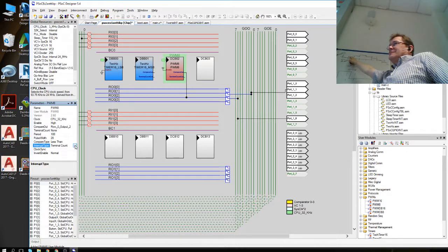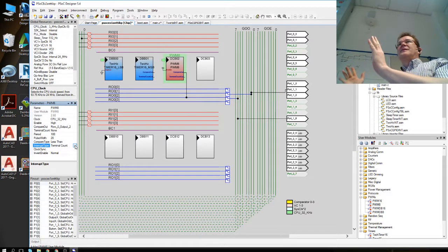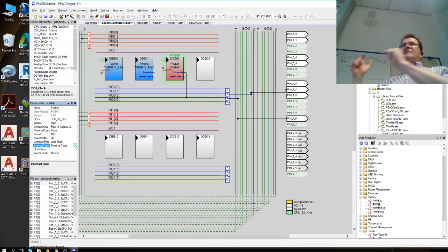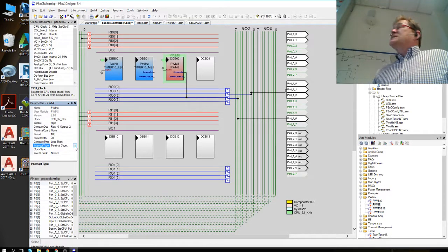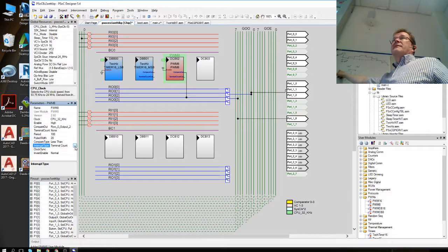But there's only one delay of 1 for that command, and it's the same delay in every single one. So it still does the same. In this case, it doesn't really matter. If you use the compare true kind, then when it starts comparing and you get the first true, you have the interrupt, and then you will change the compare value for the next round. Okay.